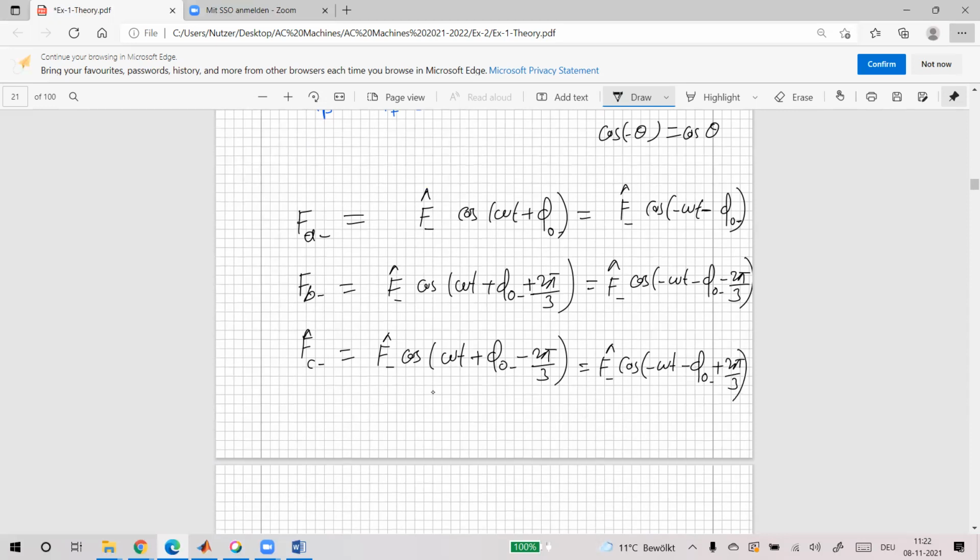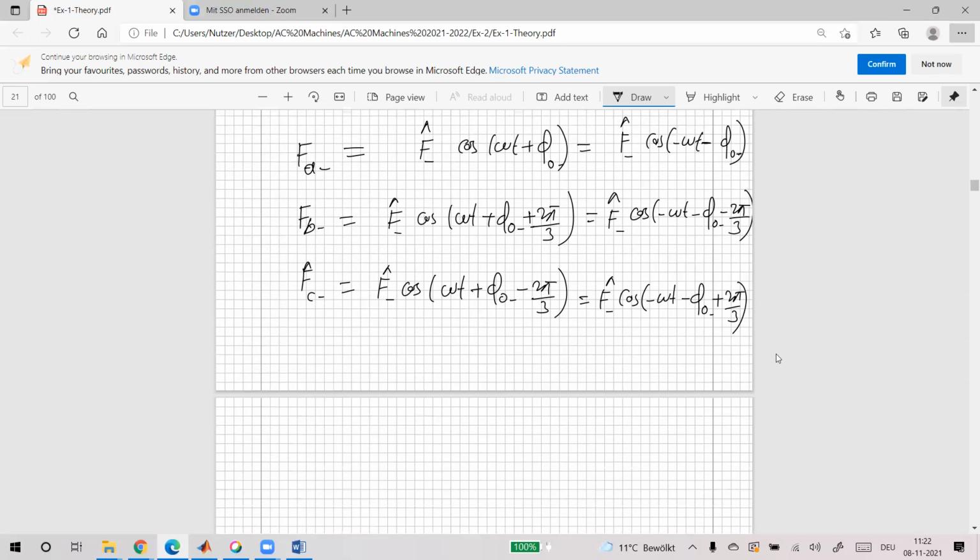Okay. Now, does it look like positive sequence phase difference? Like the first phase does not have any phase difference, second phase minus 2 pi by 3, then the third phase 2 pi by 3. So in alpha beta frame, alpha beta minus, let's say, can I write it like this? E power j into minus omega t, sorry, not plus, minus phi naught. Is it okay? Using the same structure for positive sequence?